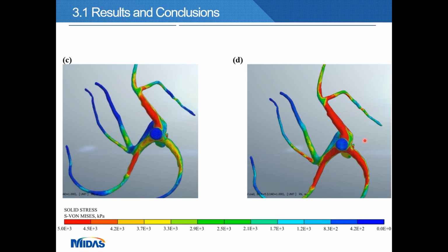In this case, the results indicate that only parts of the entire length of the roots offer resistance. The magnitude of the resistance of the effective root lengths was strongly influenced by the soil elastic modulus. So it means that it will be strongly related to the matric suction or the unsaturated condition.